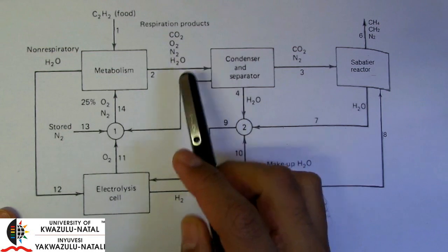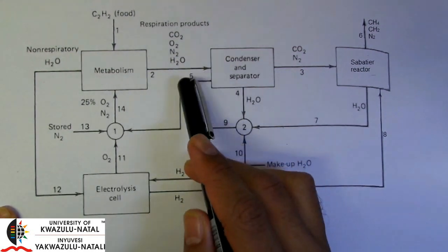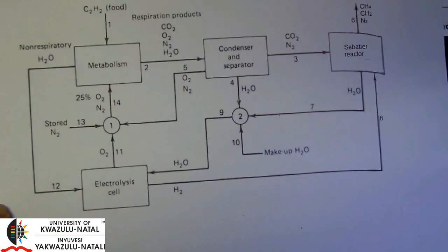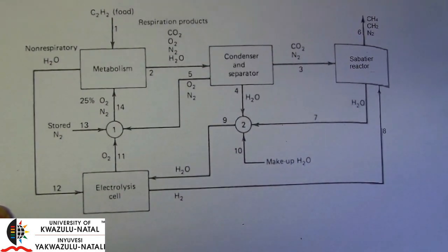So we would like to minimize the amount of flow meters and also composition measurement that will be necessary. Okay, so an engineer's solution will be to take as little amount of measurements as necessary and calculate the flow and compositions using rigorous and scientifically sound equations and computations. Flow meters can cost up to $1,200 or even $1,500 US dollars or more.